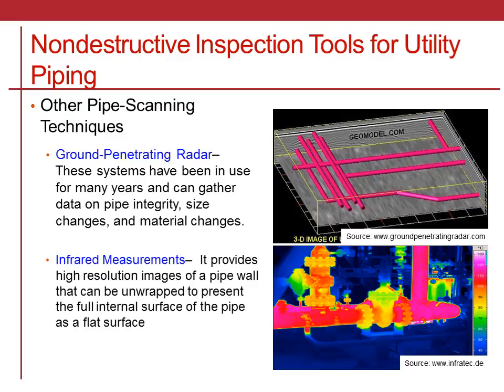The uneven heating and cooling of a pipe wall or a pipe liner can indicate variation in pipe wall thickness, the bonding of a liner to the pipe wall, or the presence of a soil void outside the pipe. These two methods can be applied during operation, but determining material type and other characteristics is usually not possible.